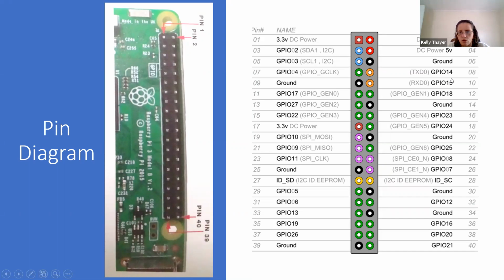And what you do is you'll hook that to the rail on the breadboard, which basically means it's like one wire that you can electrify so that you can pull power off of that for the various things that are in your circuit. So we'll be hooking up to one of these. And also, in order to complete a circuit, you need to also have the ground to bring it around. So you see that we have a couple of ground pins available as well. So that's what the pins mean, and that gives you an idea of the kinds of things that are available on the pins. So we'll have to be addressing those pins in the code.